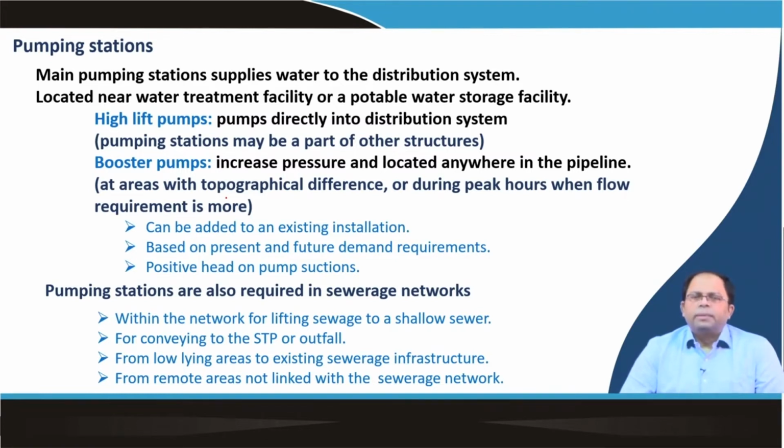requirement is more. That means during peak hours, everybody is using the tap at the same point of time. So, there is a huge amount of flow required at that point, and that also results in dropping of the pressure. So, that is also when we need to run this kind of pump to boost the pressure inside the water network. So, these are the two conditions when we actually use a booster pump.